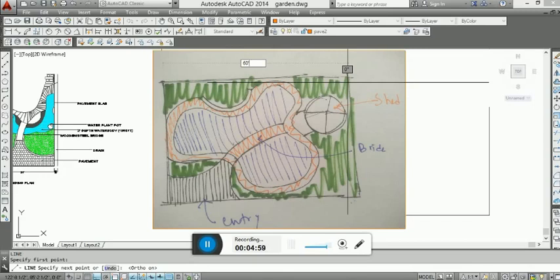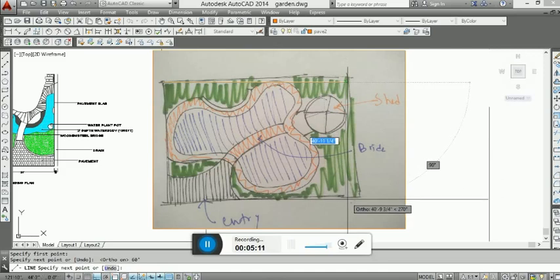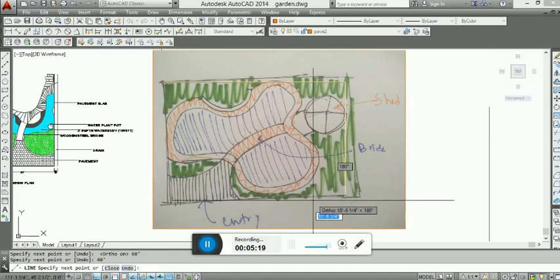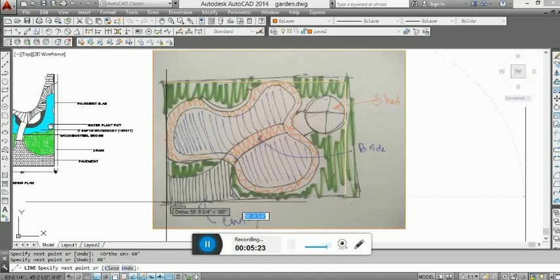So I am giving 60 feet, a straight line dimension, 60 feet space. So this is the line of 60 feet, and then again I am moving my mouse near the end point and I see it will be nearly 40 feet, so I'm giving 40 feet. And then again on the left side, if it is a rectangular site, it will be again 60 feet.